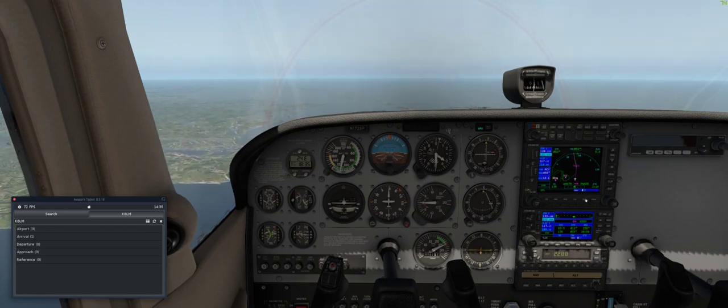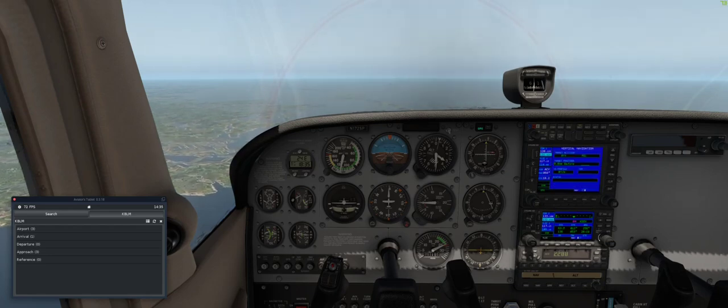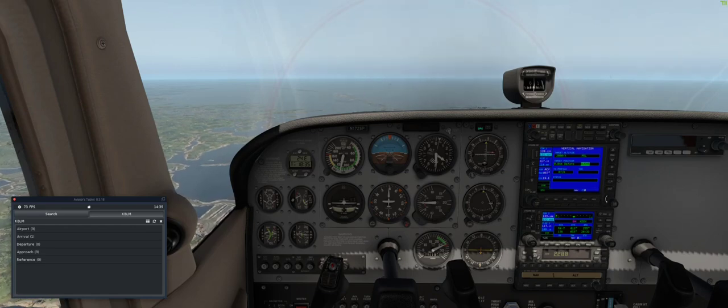Well, it kind of will. We've got this VNAV page. This doesn't tell it to do it, but it is kind of a calculator to help you understand what you need to do. So we said we want to be at 2,000 feet MSL at WUDAB. 0 nautical miles before WUDAB is effectively at WUDAB. And this aircraft typically descends at about 800 feet per minute, I believe.